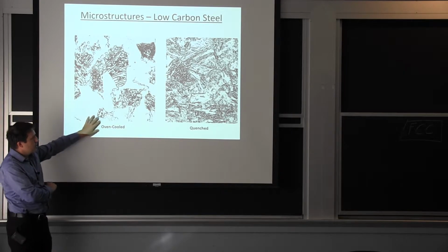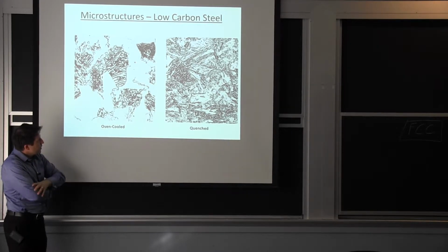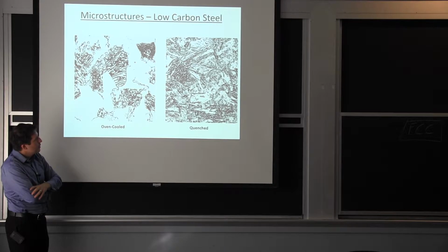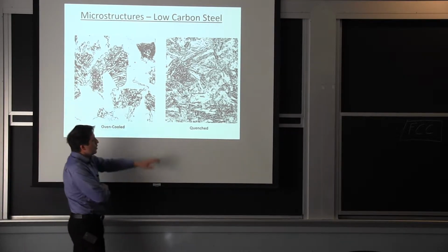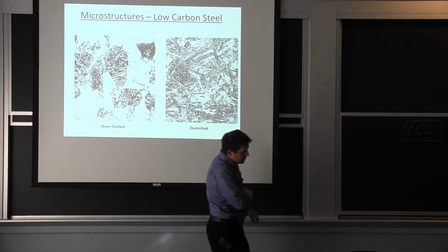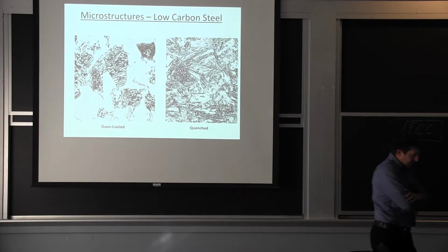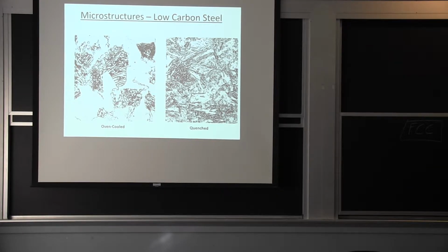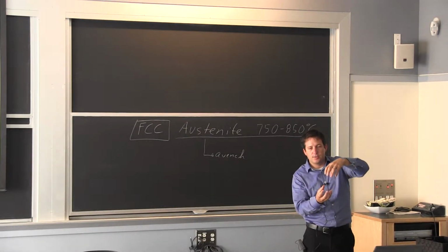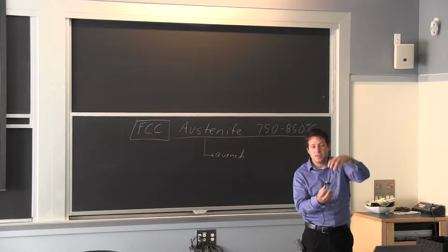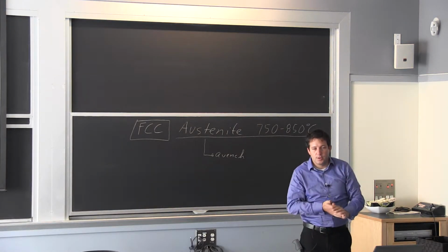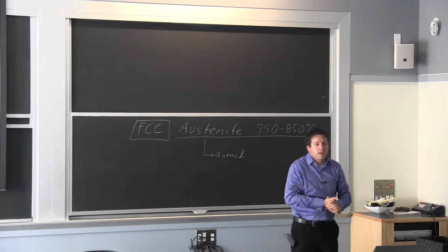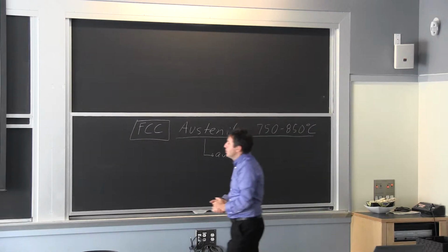So here I was talking about cooling quickly, like the image shows. If you go very quickly in your cooling, you quench in water, for example, you form that martensite, and that's the tetragonal phase. So if you think of something very cubic that has all this symmetry, and then all of a sudden one side becomes longer, the reason it becomes longer, there's a little piece of carbon that comes in there, and then all of a sudden you lose a lot of symmetry, you lose a lot of slip planes, and that is the martensite.